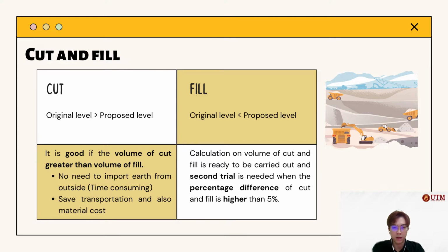Calculation on volume of cut and fill is ready to be carried out, and a second trial is needed when the percentage difference of cut and fill is higher than 5%.